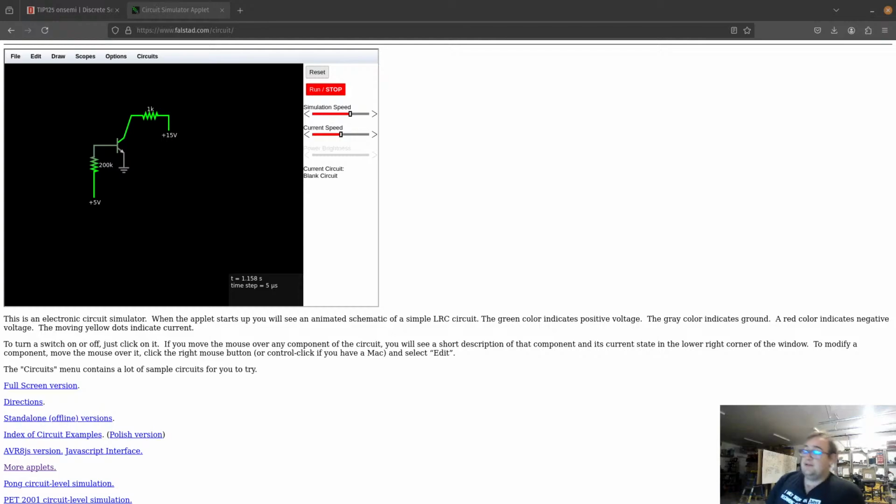And by doing that, we make about 25 microamps, I said. But it turned out to be 22.4 or something, the Falstad simulator said. Now, the reason why I would have calculated that is because, like I said here, there's a diode drop. It would be factoring in on this transistor. So that's why.